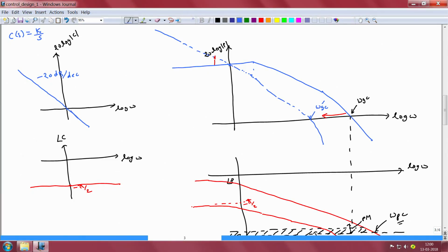So, what can be done to address this issue? What we can do, if we return to the Bode plot of the controller again, is to note that if this decreasing characteristic were not to be there, at least if it was not attenuating the gain of the plant, but the controller neither added gain nor attenuated the gain, then at least we would have a bandwidth for the closed loop system that would be comparable to that of the plant itself. How do we accomplish this objective? We accomplish this by placing a 0 at the location where the gain of the controller crosses over.